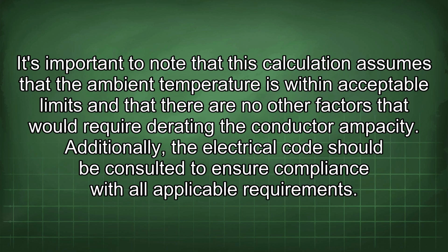It's important to note that this calculation assumes that the ambient temperature is within acceptable limits and that there are no other factors that would require derating the conductor ampacity. Additionally, the electrical code should be consulted to ensure compliance with all applicable requirements.